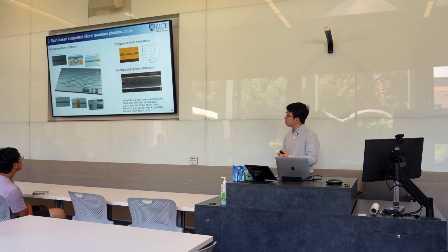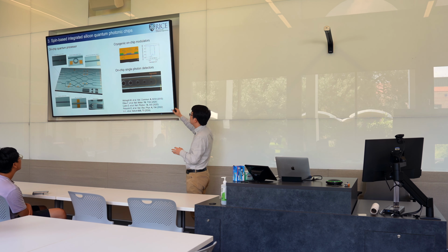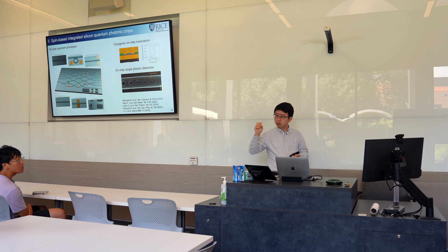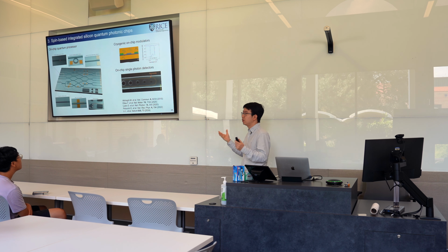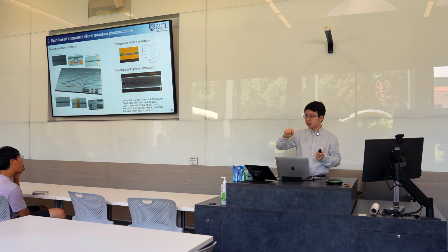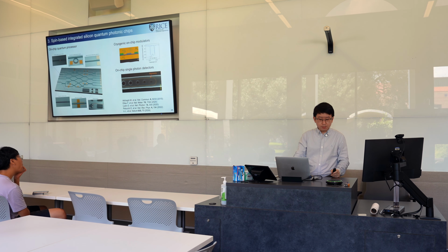And as I mentioned, we also want to have the nanowire single photon detectors there. So people have tried to pattern this superconducting nanowire there. The idea is that if a single photon is absorbed by the superconducting nanowire, it will break the superconducting phase of this nanowire. So now if you flow a current through this nanowire, you will see a voltage spike whenever a photon is absorbed and breaks the superconducting phase. Okay. So these are part number 3, where we want to utilize silicon as our platform to hold many quantum components to make a quantum photonic chip.